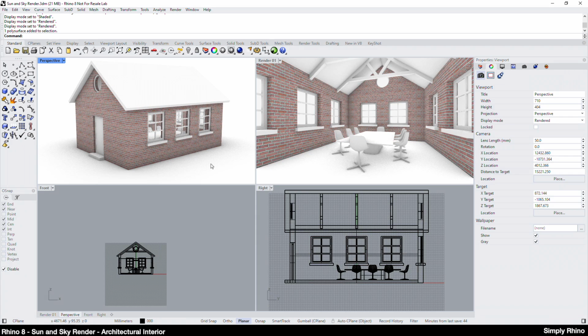The Rhino materials with textures mostly use a mapping type called WCS or WCS box mapping. WCS stands for World Coordinate System, and by using this system, textures like this brick material appear at the correct size without the user having to modify the texture mapping. And box mapping works well with simple planar geometry. Now, of course, there are many occasions where custom mapping is needed to take full control of the texture. But for this video, I'll just be using the default projection.